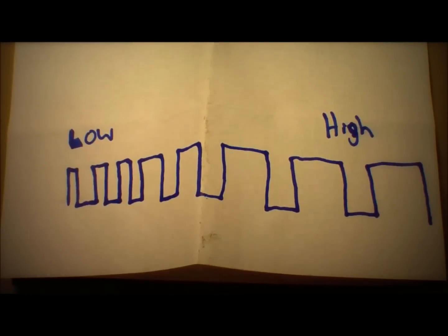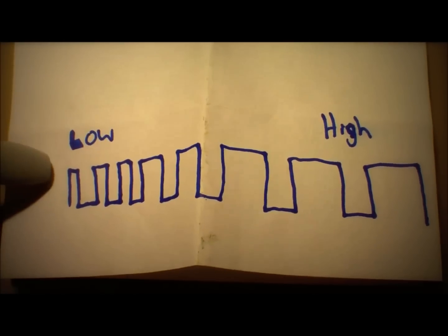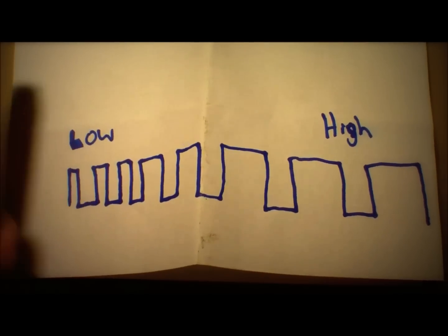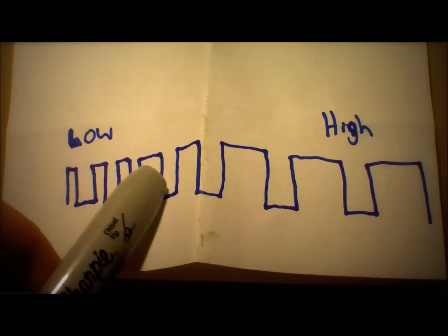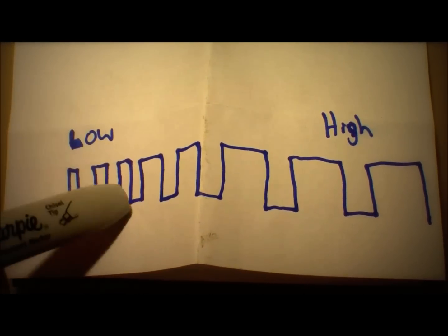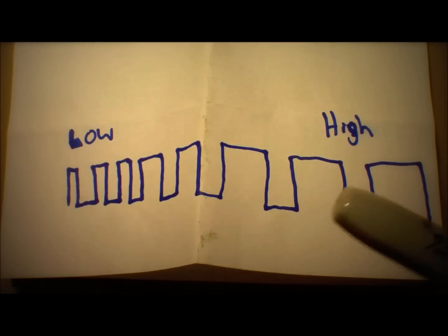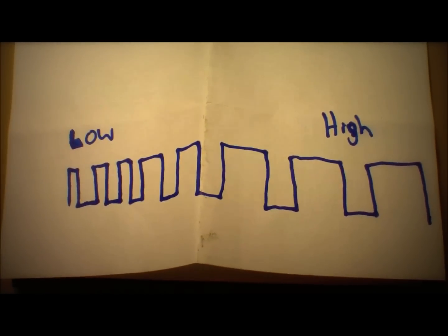Okay, so since we're using a digital pin, it can only be either on or off. There's no in between. So basically what's happening is the LED is on and then off for a long period of time, and then it turns back on and off, and that period of time that it's waiting in between is getting smaller and smaller. So the LED is actually on more than it is off, and that's what's increasing the brightness. So when it gets to the end here, the period of time that it's waiting in between gets really short, and the time that it's on is really long, and that's what makes the LED appear very bright. And when that period of time is very long, that's what makes the LED appear very low, but it's happening so quickly that you can't even see it.